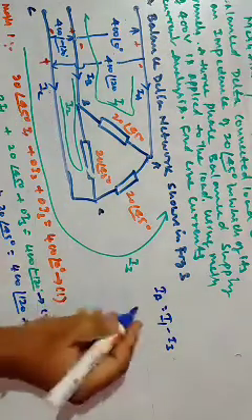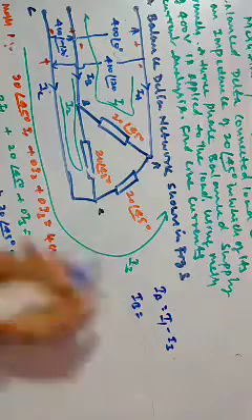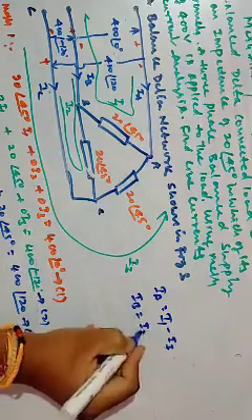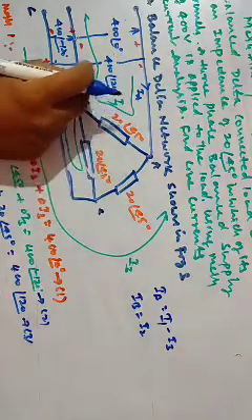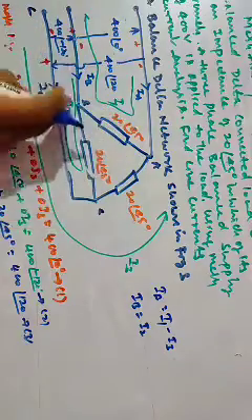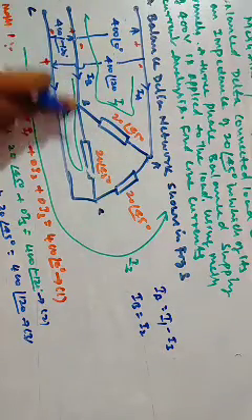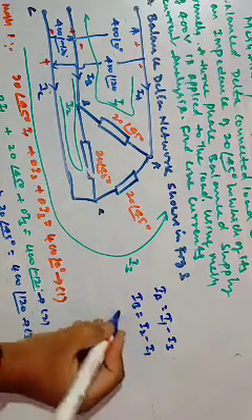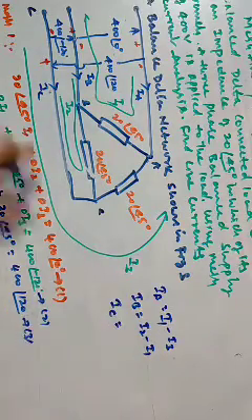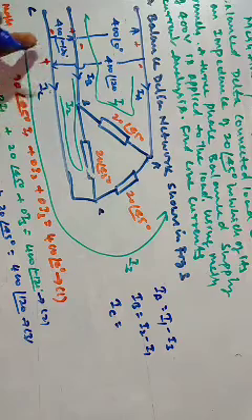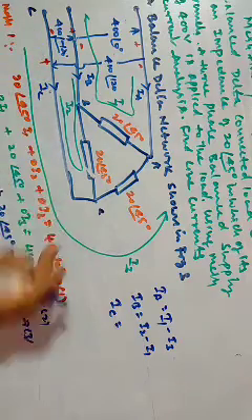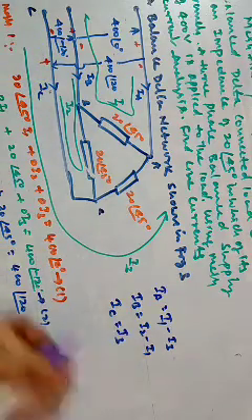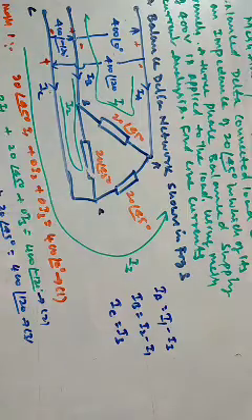Similarly, for IB, I2 is in this direction and I1 is opposing, so IB is I2 minus I1. Similarly, for the line current IC, I3 is in the direction, so IC is I3 minus I2, as I2 is opposing.